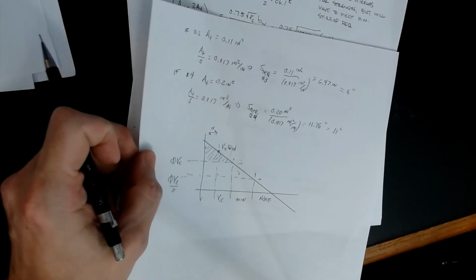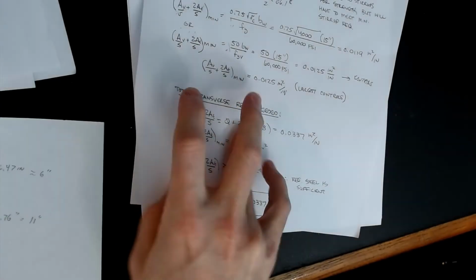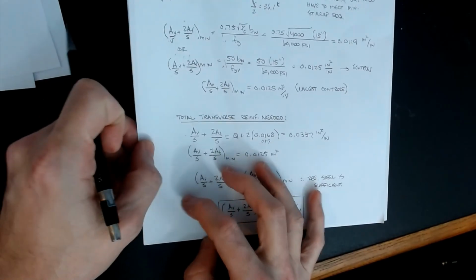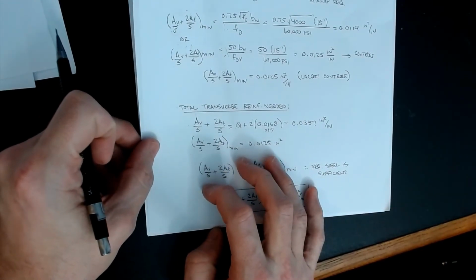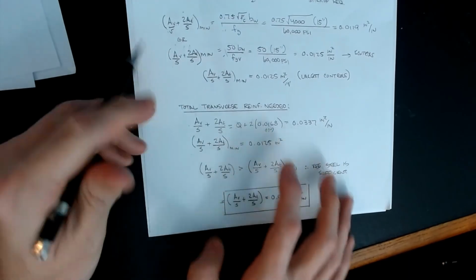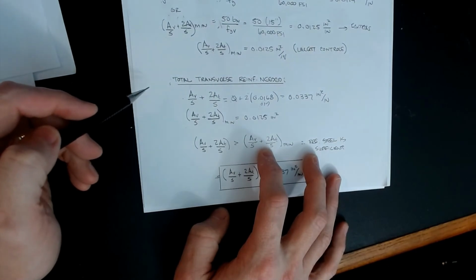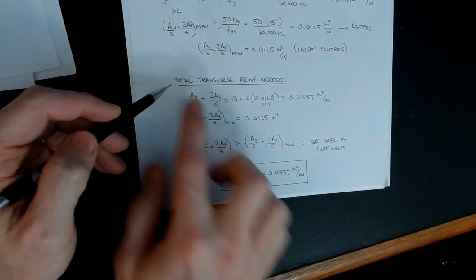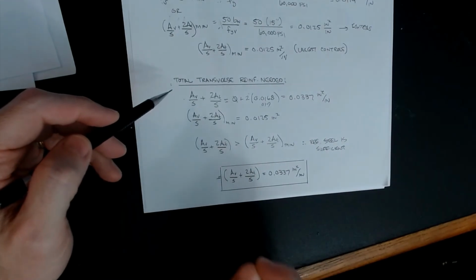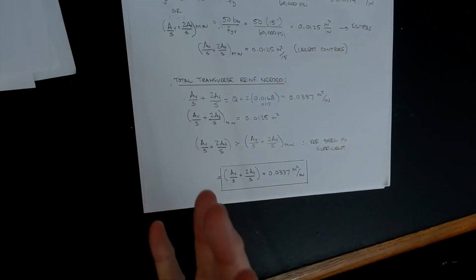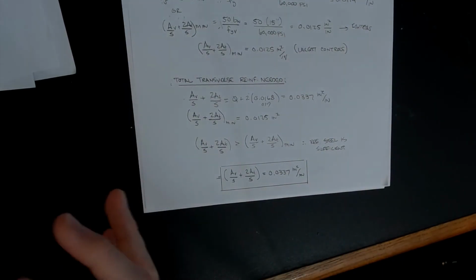Okay. All right. So I'm going to pause there. The next thing that we've got to check, we've got 2 other steps that we've got to do, and I'm going to do both of these in the next video on this. We've done the transverse reinforcement. Now we've got to go in and do the longitudinal requirement. Because we're going to choose an At over s and set that value, and then I'm going to set that value into the longitudinal area requirement to get the calculation. Remember how we manipulated that formula and set the 2 Tn's together? And then I could write one in terms of the other. And so that's what I'm going to do. And then with that, we'll be able to get our longitudinal requirement.